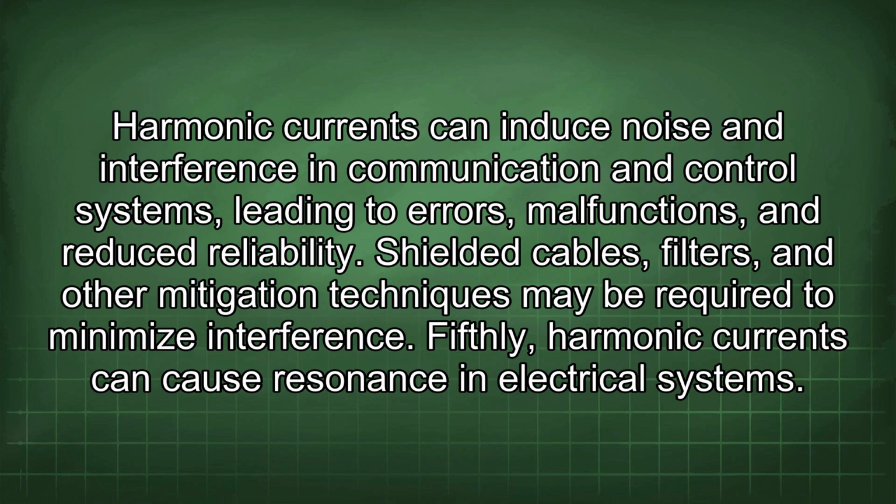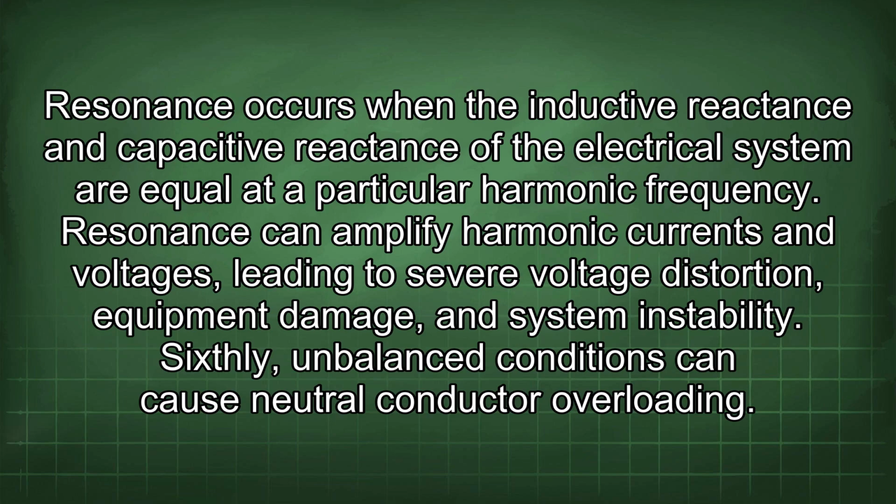Fifthly, harmonic currents can cause resonance in electrical systems. Resonance occurs when the inductive reactance and capacitive reactance of the electrical system are equal at a particular harmonic frequency. Resonance can amplify harmonic currents and voltages, leading to severe voltage distortion, equipment damage, and system instability.